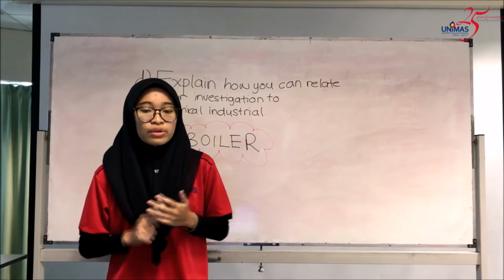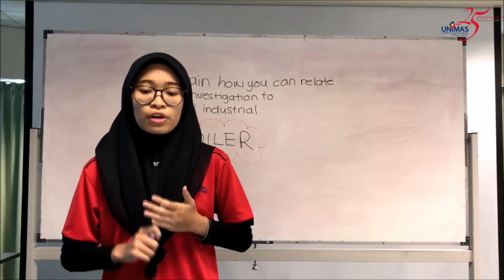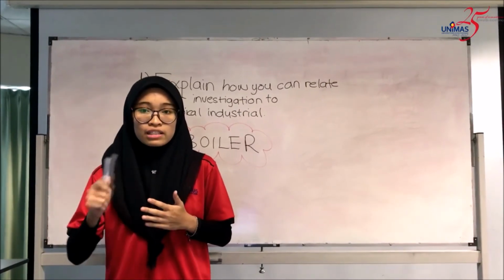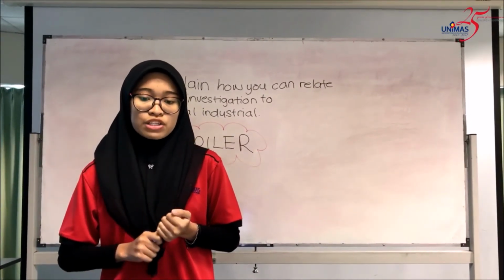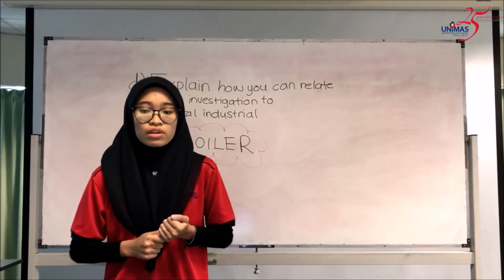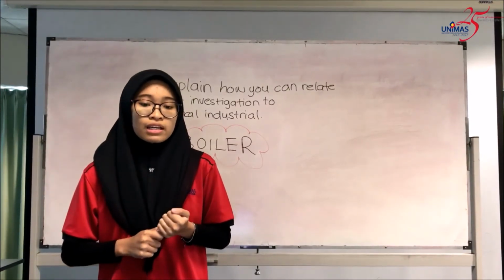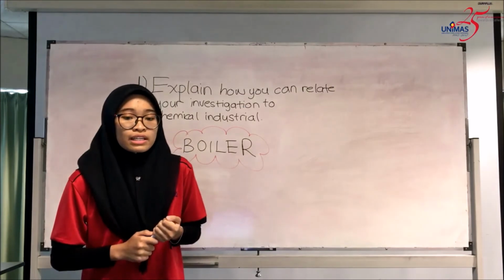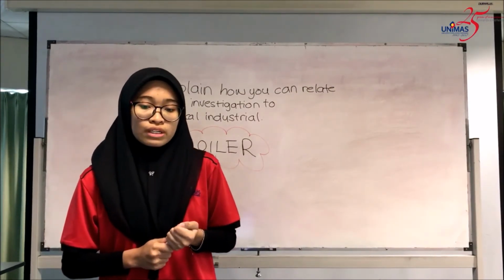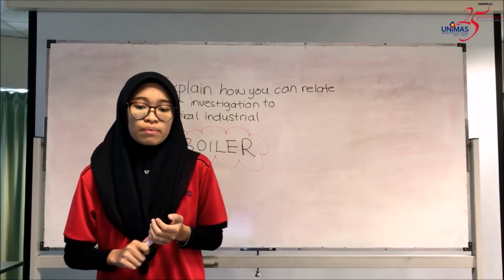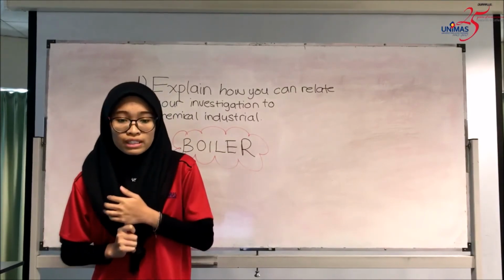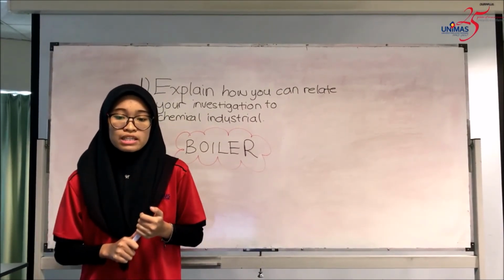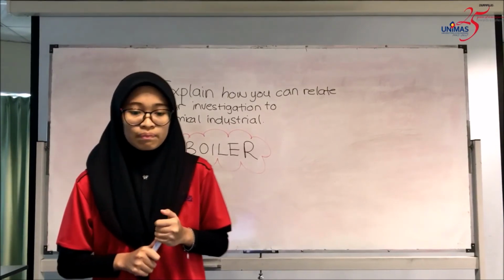For example, to heat your home, you switch on the boiler with an electric switch. A valve opens and the gas enters a sealed combustion chamber in the boiler through lots of small jets, and an electric ignition system sets them alight. The gas jets lay onto a heat exchanger connected to a pipe carrying cold water. Then the heat exchanger takes the heat energy from the gas jets and heats the water.